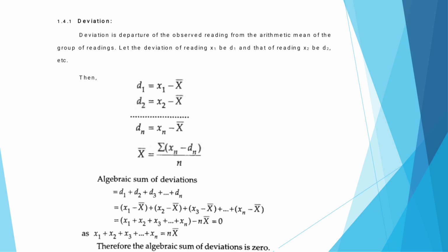Also checking the time of the day, buying cloth, purchasing groceries or calculating the power bills through an energy meter. Without calibration, the accuracy and reliability of every single one of these measurements could be highly doubtful. So calibration provides the assurance that the measuring device is displaying an accurate and reliable value.